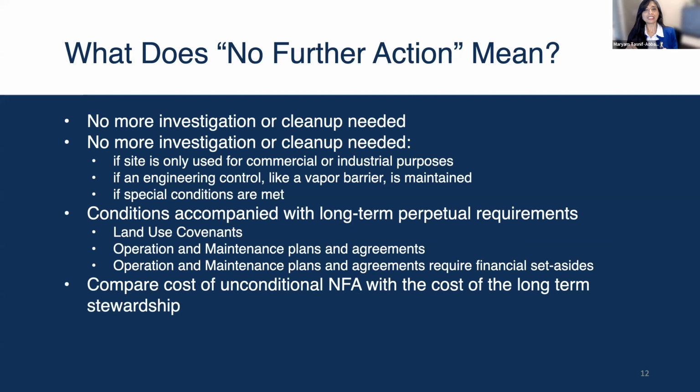So conditions like the site can only be used for commercial or industrial purposes, or if there is some kind of barrier in place, then it has to be maintained. And there may be other special conditions like a special use, like a park use that may be a little bit different than a residential use or a commercial use. When we have these no further action with conditions, there are long-term perpetual requirements in place to make sure the land is being used and is compatible with what our endpoint decision was. So this could mean deed restrictions and long-term operation and maintenance plans.